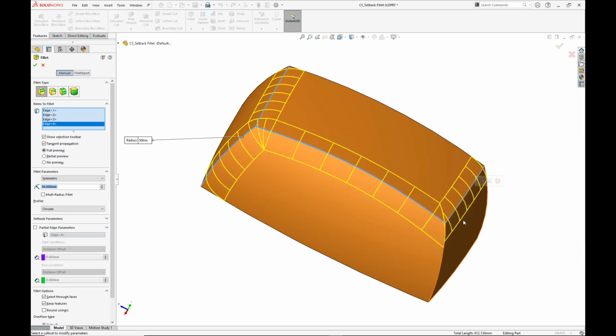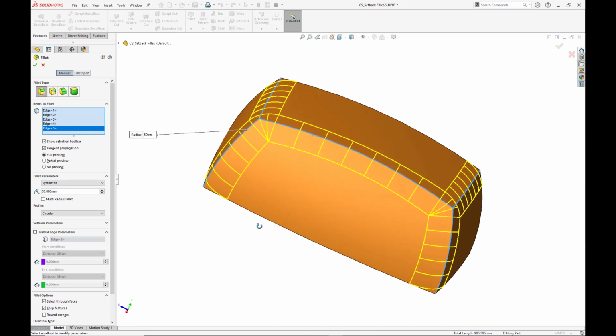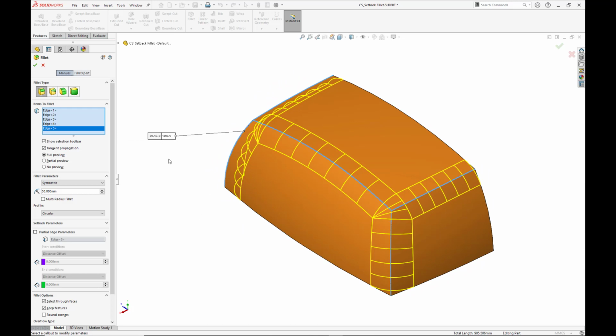Now with some designs, you do want to have multiple fillets, and trying to individually create them and mesh them together tends to be an overcomplicated process. But inside of the options dialog, you have something called Multiradius Fillet down over here. When you click on that, you're going to get some additional on-screen tags that pop up here, and you can just say, maybe I want to have that leading edge at like 12.5 as an example. Then I'll hit tab, and you can see it update.